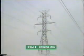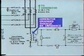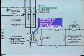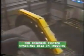Now at this point, let's briefly summarize the methods of grounding which you will encounter. Solid grounding. This is the case with most utility systems above 40 kV. Generators may be grounded through an impedance so as to limit the magnitude of fault current. Non-grounded systems are sometimes used in industry where a continuous power supply is required.